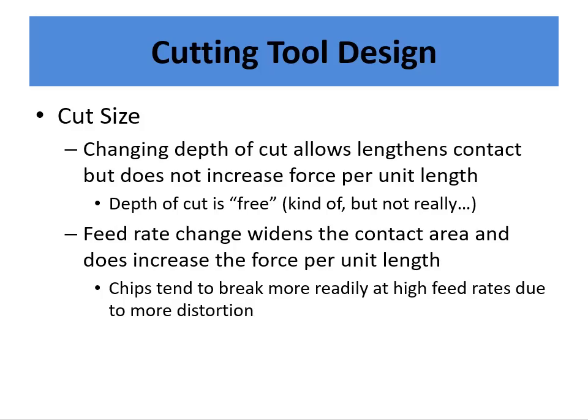Okay, and if you increase your feed rate, essentially you're trying to cover the same amount of ground in a shorter amount of time. So you're going to have to increase the force to do that. And that's where you can mechanically break chips as well. Not only can you get the heat if you increase your speed, but if you increase your feed rate, how much you're grabbing per tooth, sometimes you can break more because you can get some distortion that happens.